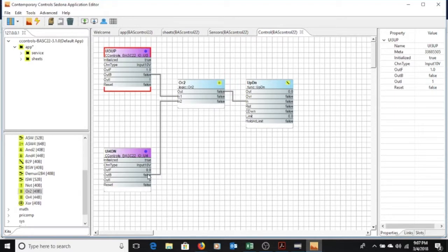And then if we want to count down, the reason we have to use this on a countdown over here is because to count down, you not only have to hit the down, but you have to pulse the input. But seeing as we can only get one thing to go into each input, we can have multiple outputs, one thing into an input, we have to use an OR to stage these. It's like stepping it away, so this block or this block is allowed to pulse the input. That's why we use this, that's why we're going that way.